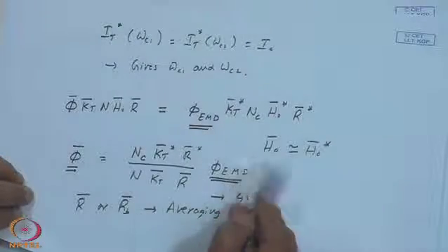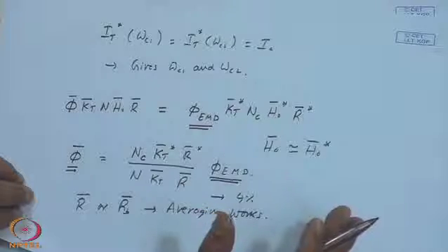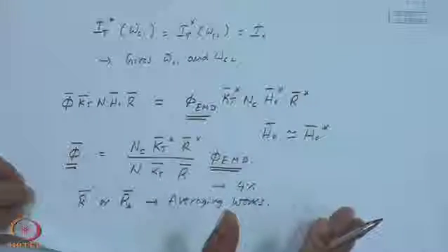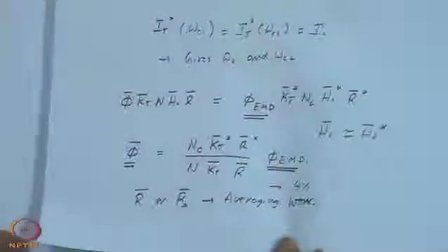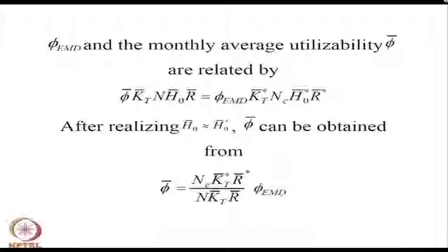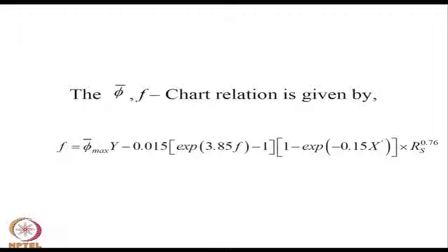And this has the advantage that, though it may be a long expression, it can be analytically expressed with one integration. For certain two of the concentrating collector modes, it is not analytically integrable, but nevertheless even making hour by hour calculation for one day is far simpler than going for all the 30 days. So, we have a fairly general method to evaluate the monthly average daily utilizability.